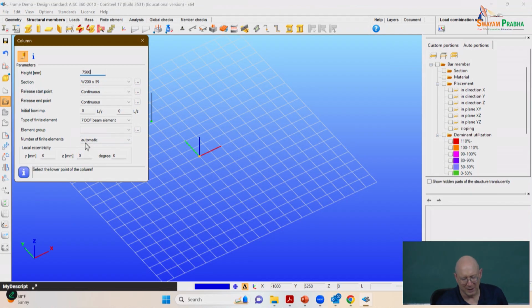Here we're going to explore. So what do they mean by 7 degree of freedom beam element? Okay, so every node has 3 displacements, 3 rotations, and then what we call a warping degree of freedom. How do you define the warping? Yeah, so the warping, if it's an I section, it's simplest. So warping is simply a cross bending of the flanges. So warping is when the flanges are bending in opposite directions. So you can add that to the lateral bending of the flanges.